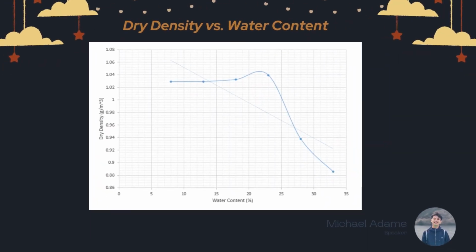By having this kind of result in the experiment, the maximum dry density was determined at the point the soil has 23% water content of its original mass. It also met the desired shape of a compaction curve of a compaction test of soil, which is expected to be parabolic. Its vertex point is the maximum dry density at the optimal water content.